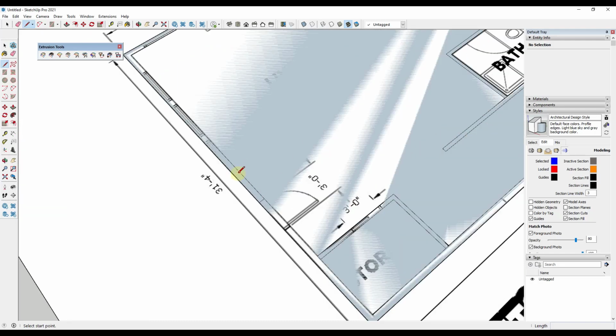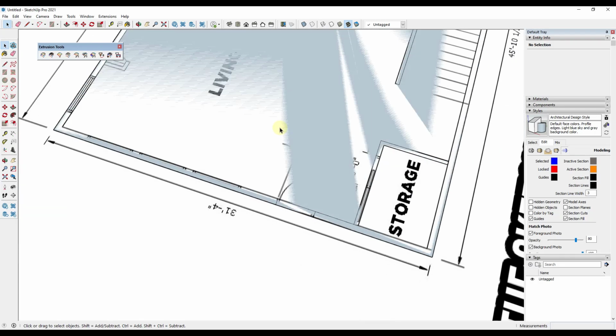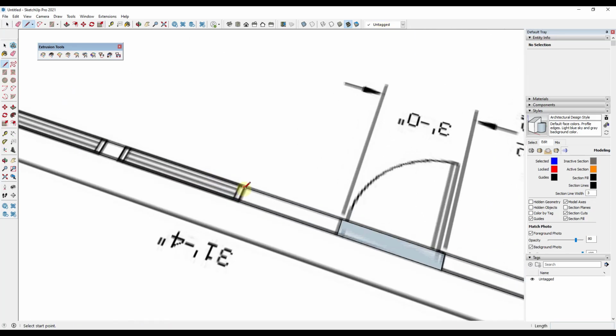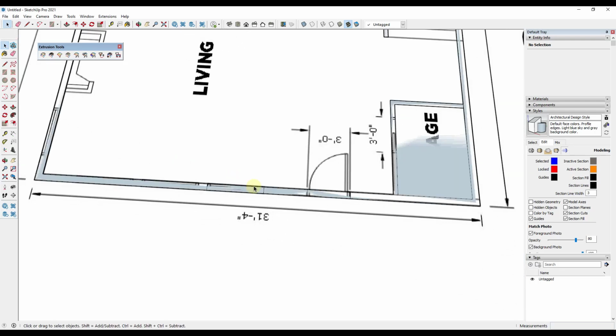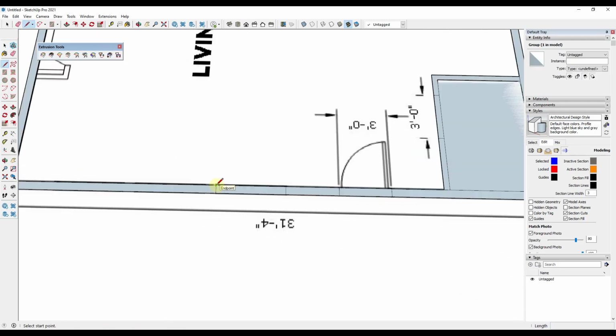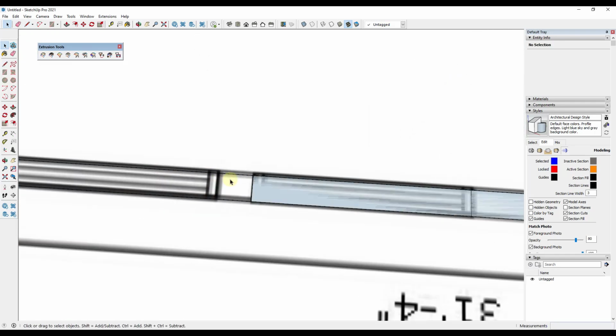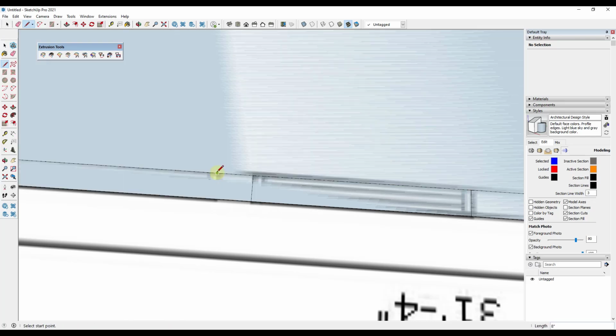So for these windows, for example, I'm just going to come in here, delete this out, and actually I'm going to delete this face. It'll just heal back in when I draw across this. So now I have an edge here. I'm just going to draw an edge right here. So in the case of these windows, I'm going to cheat a little bit, and I guess it's not cheating as much as using smart modeling practices, but what I want to do is draw a little guide edge right here. It's going to be about 8 inches long because that's the spacing between the windows.